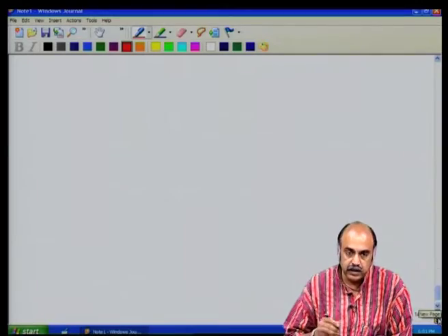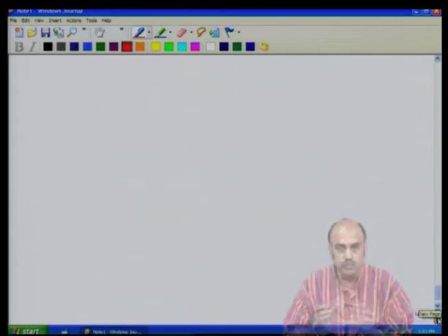Now, these printed inductors and capacitors can be used at the ends of the tracks to adjust the values of the wave impedances in order to avoid the reflection problems. Okay. This is one issue. Another problem that you would see in a printed circuit board when many printed circuit boards are put together to form a bigger system is that of connectors.